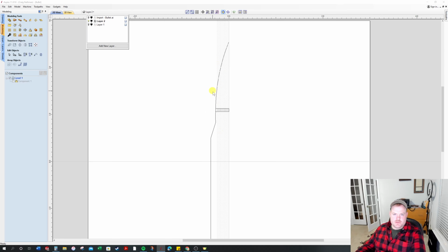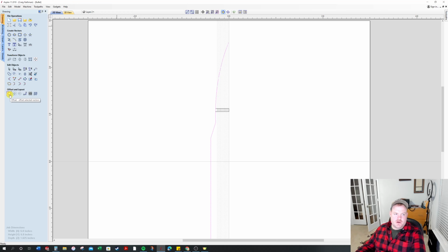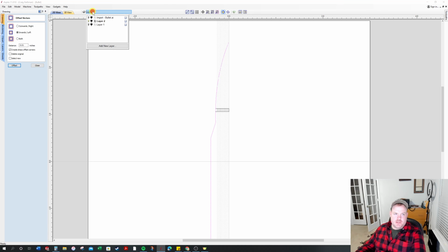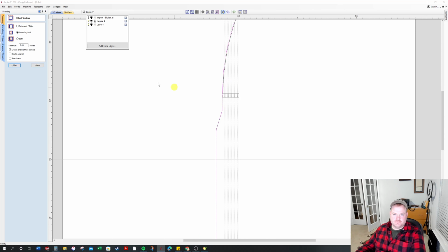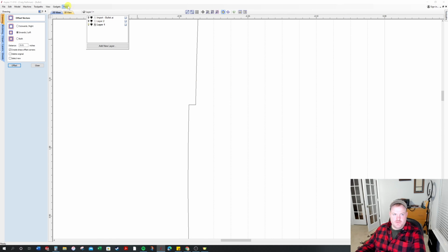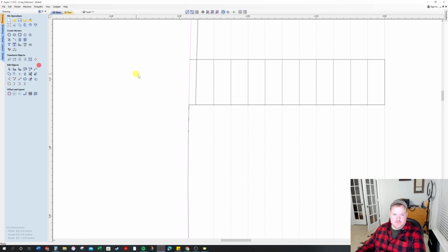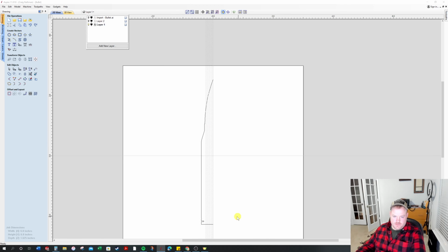I took this sketch here, or vector, and then I went to the drawing tab and I offset it. I did that by 0.01. And when I did that, it gave me this. So I'm going to turn this off. And then I also trimmed it down. So I trimmed it. Let's close out of this. I trimmed it with these vectors here to pull it in to give me a little bit of a lip. See there?